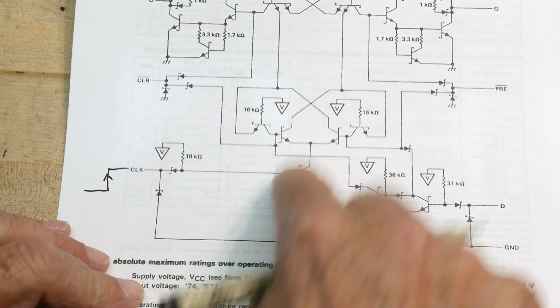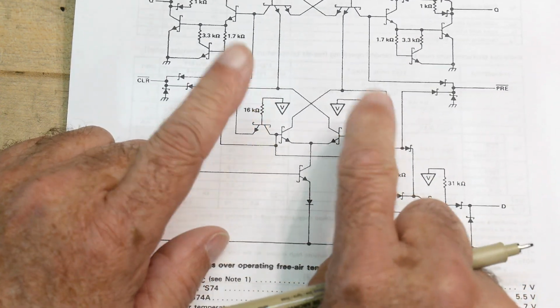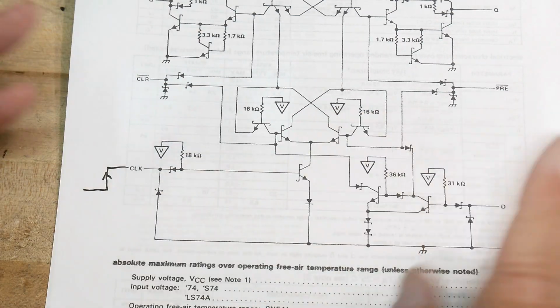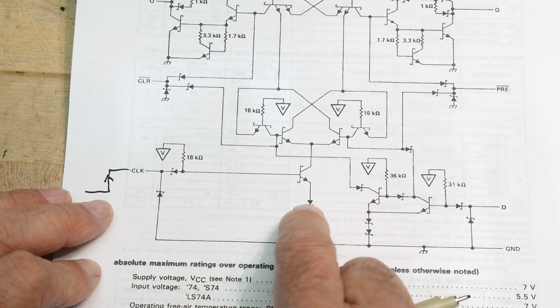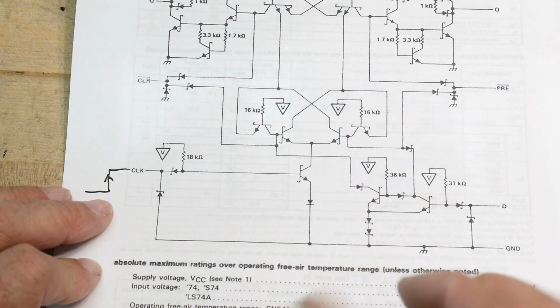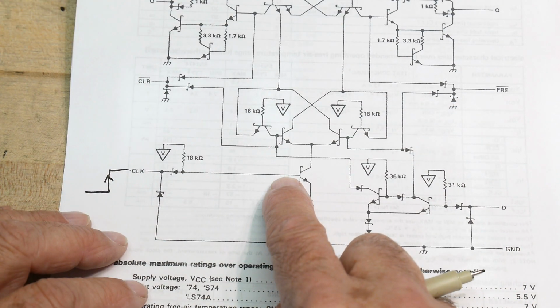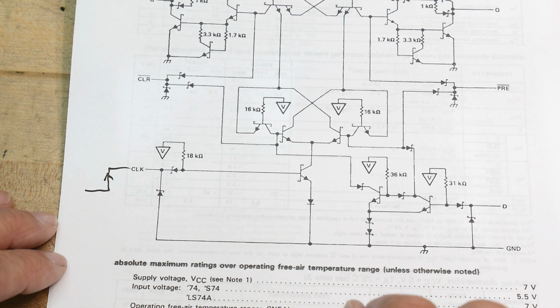No matter if you enable it, or you stop enabling it, or you enable it again, once this flip-flop is set, it's set, okay? And so once it gets set, it doesn't matter how many times you see an edge here, okay? I should actually say no matter how often you see a high state here, the rest of the circuit won't do anything, okay?